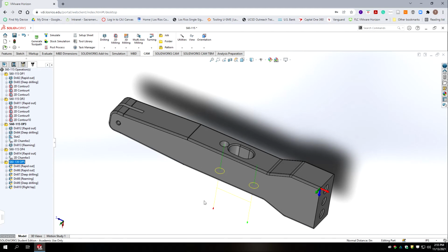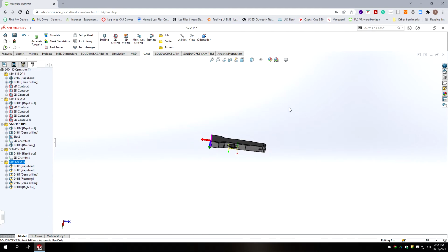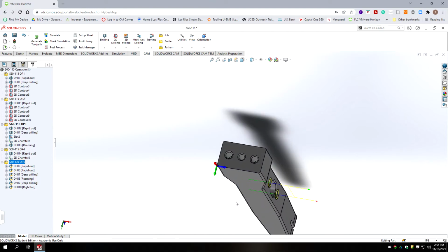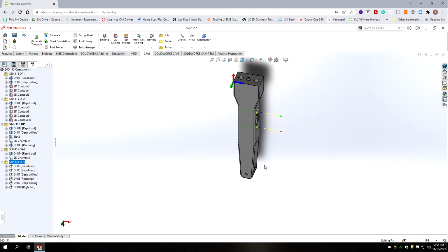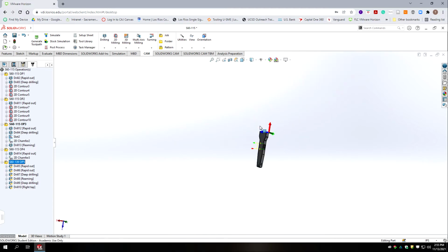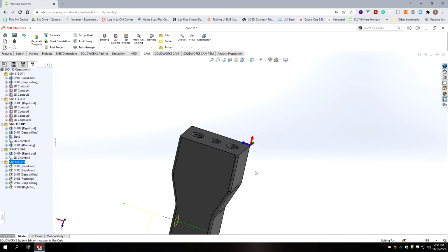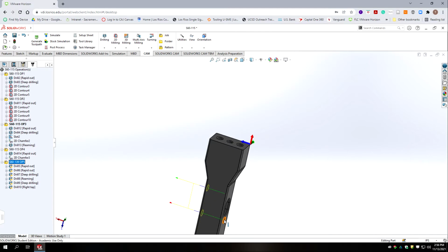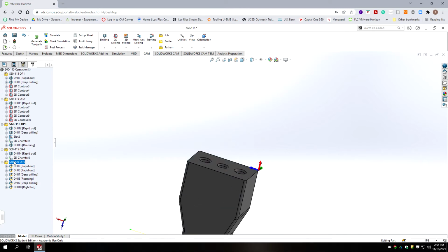Now let's go on to op 5. We're looking at machining the end here. We want to put the side with the point, so we have it facing this way with the single hole on the right. Now there's a variety of ways we can handle this. We could do it like the other part we did. Fortunately, this part has some flat edges that we can clamp to, indicate on, and use as stops. So I don't think we're going to use the same scheme we used on the 139 for our stock.